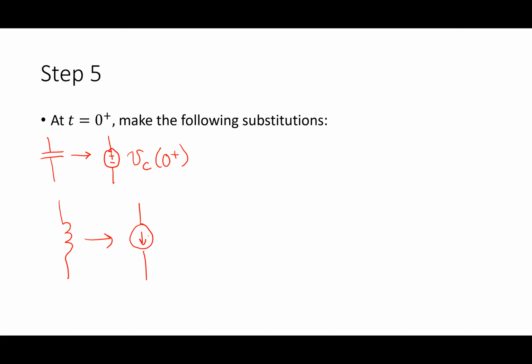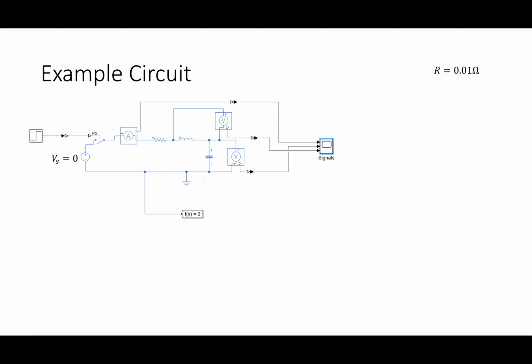All right. If the current cannot change, that guy can't be a resistor, right? Because a current through a resistor sets the voltage across the resistor, right? So for that short period of time, we say this guy looks like a current source, this guy looks like a voltage source, and we're going to use that. Okay. So let's think about it in this particular circuit.